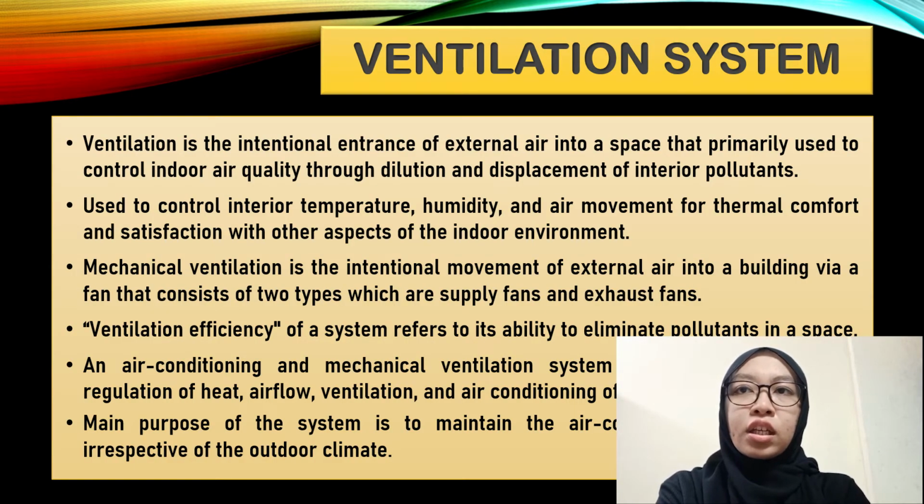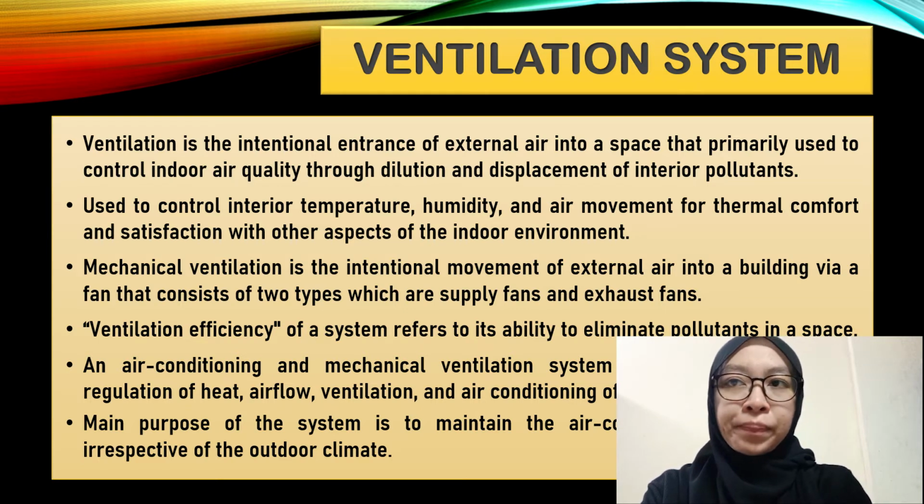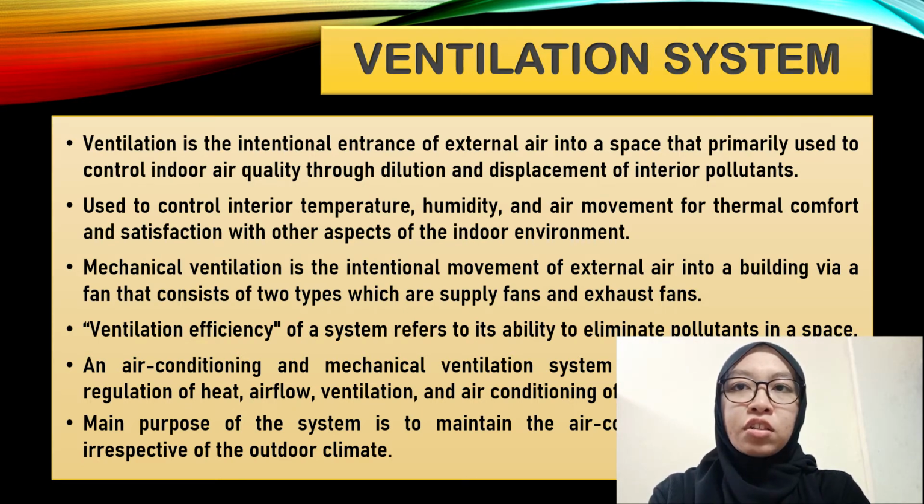Ventilation is the intentional entrance of external air into a space, primarily used to control indoor air quality through dilution and displacement of interior pollutants. It can be used to control interior temperature, humidity, and air movement for thermal comfort and satisfaction with other aspects of the indoor environment. Mechanical ventilation is the intentional movement of external air into a building via a fan, which consists of two types: supply fans and exhaust fans. Ventilation efficiency of a system refers to its ability to eliminate pollutants in a space.